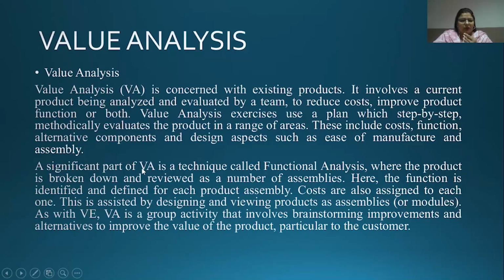A significant part of VA is a technique called functional analysis, where the product is broken down and reviewed as a number of assemblies. Here, a very important technique of value analysis is functional analysis. What we do in this analysis is break the product down into different parts, and then we review what cost will occur and how we can add to the value of the product. Here the function is identified and defined for each product assembly.